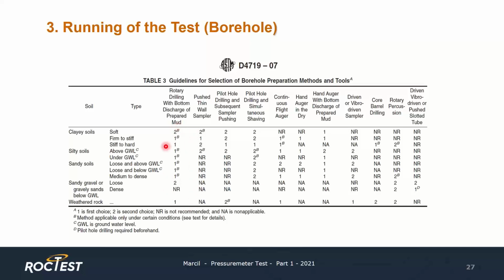Actually, it can be used in almost all types of soil, except in sandy gravel or gravelly sand, where it is not recommended, where the only option may be to use a slotted casing or a slotted tube.